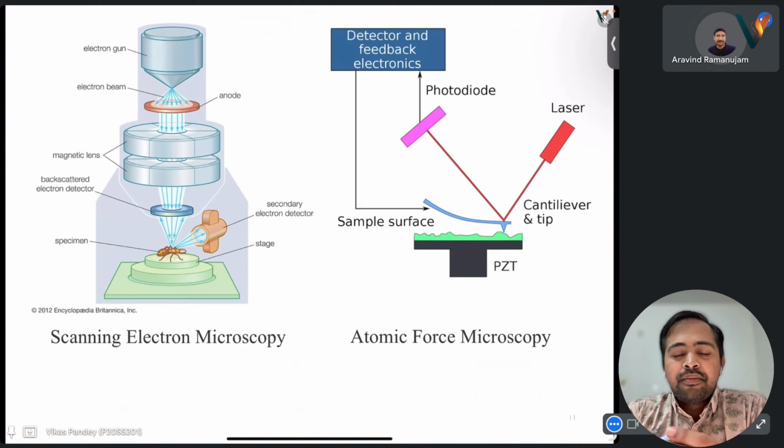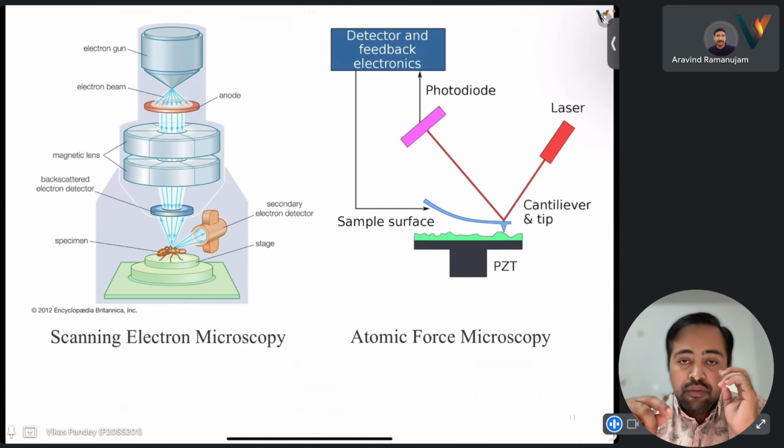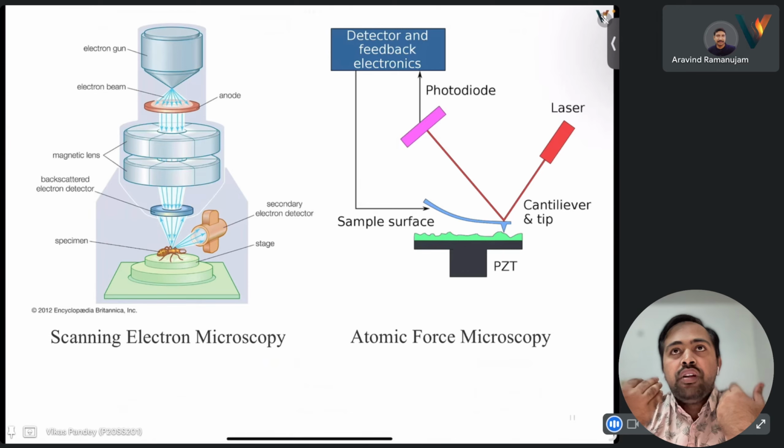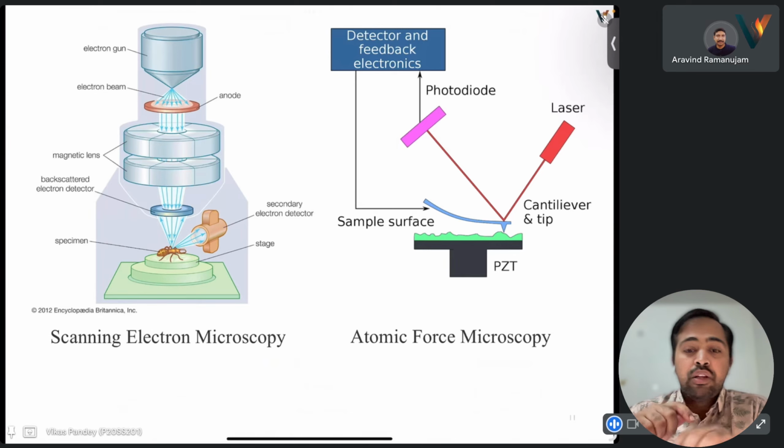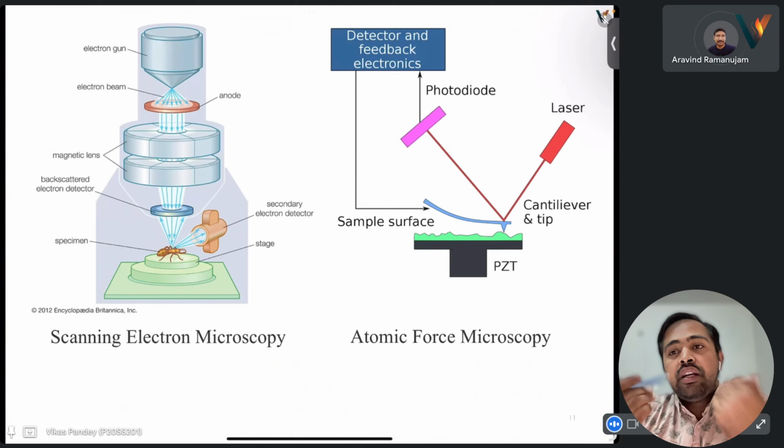For surface roughness, you should use more area, at different heights. Maybe that roughness has to be calculated using atomic force. Yes. The problem with SEM is that we can take a picture of it, or have an image of the structure at a very good resolution, but we cannot see the ups and downs, since we are detecting the reflected electrons only.